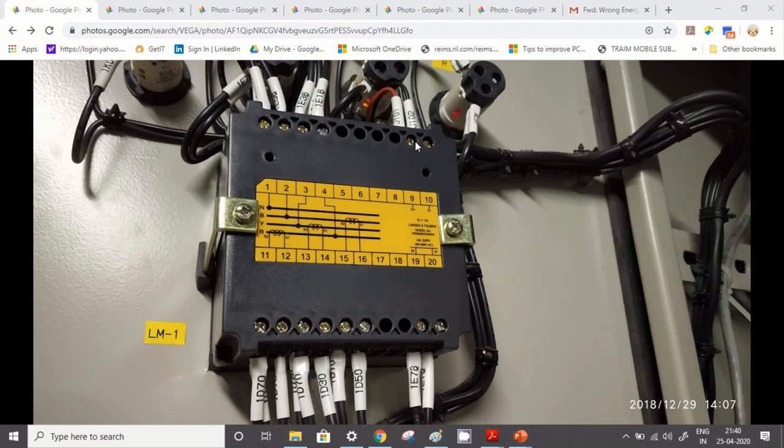And if after doing that you are getting the value there, then that means your cable is having some fault. So you have to find out the faulty cable by checking the continuity, and you have to remove that part. So this is also one basic troubleshooting. Sometimes it works because all these cables are 5 to 6 years old, and there is a chance that some strands are broken, and because of that the signal is very weak and you are not getting the value there.